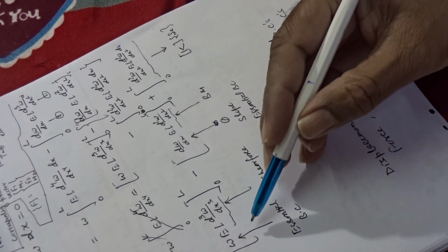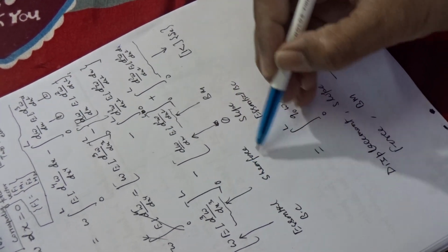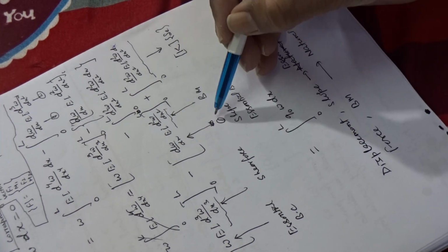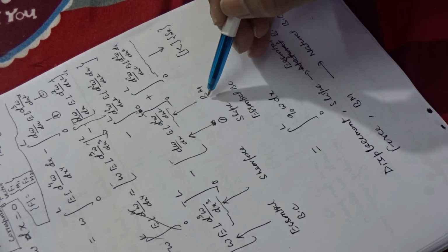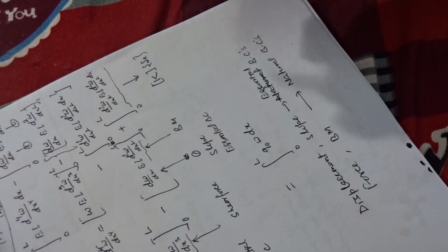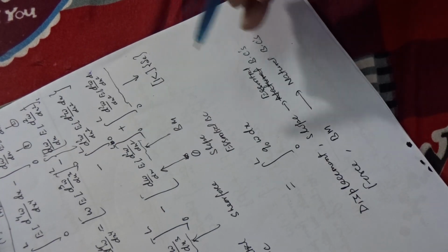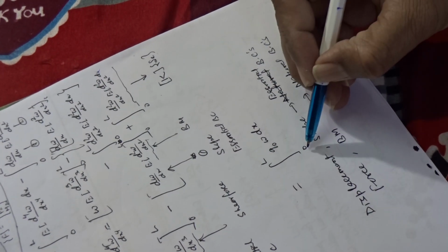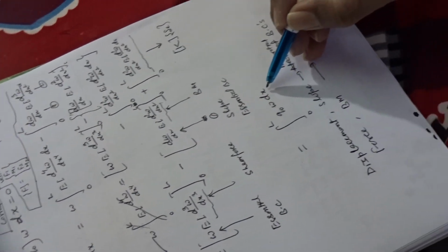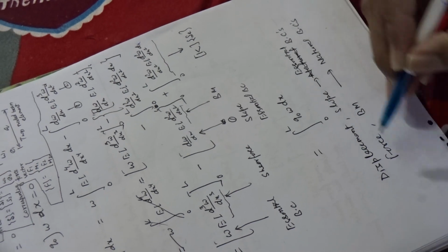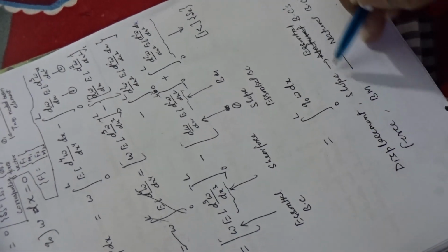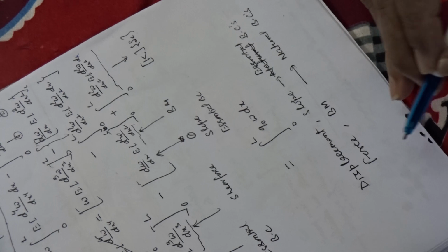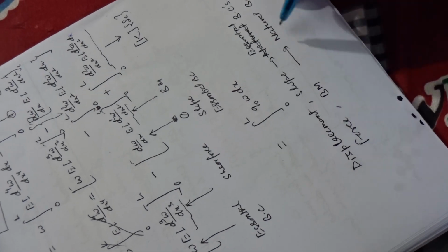w is the essential boundary condition. This one is the shear force, this one is the slope, and this one is the bending moment, and this gives the stiffness matrix, equal to the right side. This one is the force matrix, 0 to L q naught w dx. As we know, displacement and slope are the essential boundary conditions, and force and bending moment are